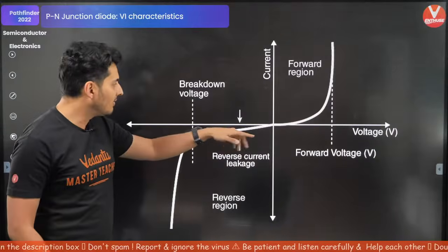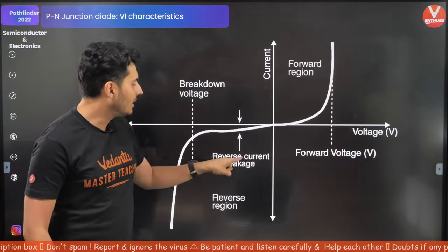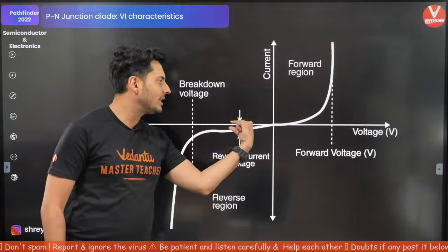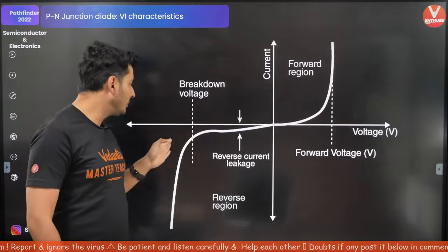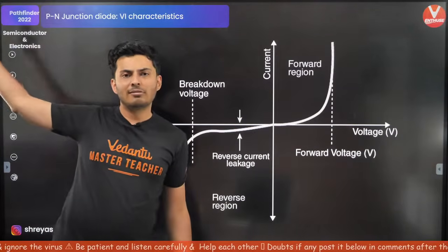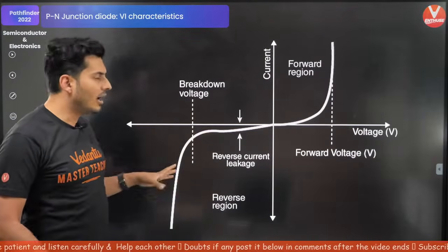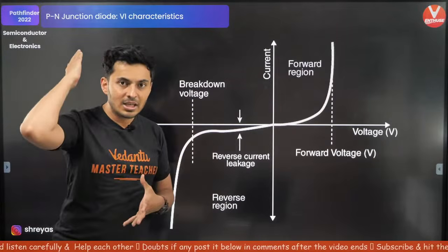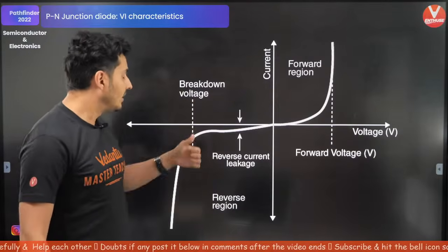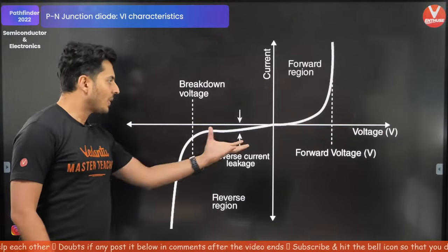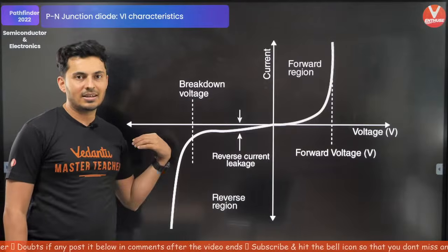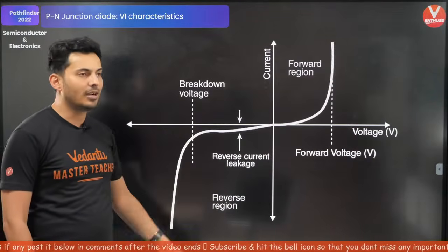And remember, in the reverse bias, you can see hardly any reverse current. That is negligible, unless and until a breakdown occurs, but that is for a very high reverse bias voltage. Only for a large reverse bias voltage will the reverse drift current break in, and you will see a huge surge of current suddenly, but that is for very high voltages.